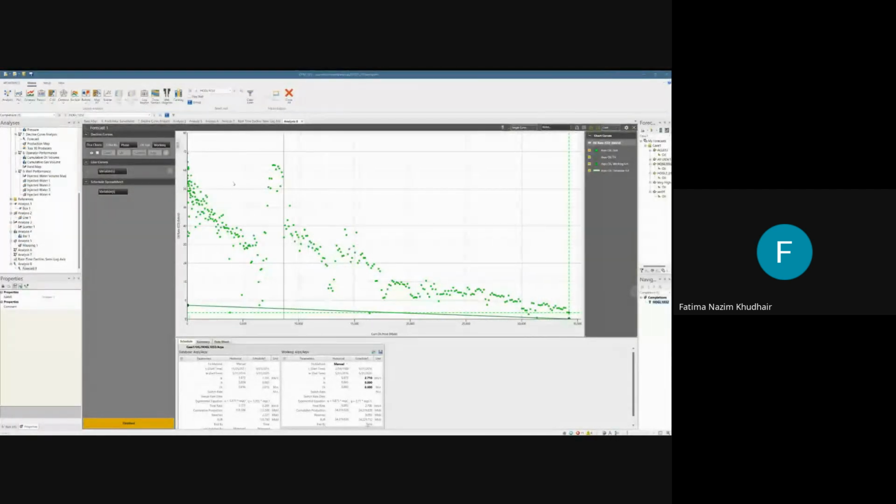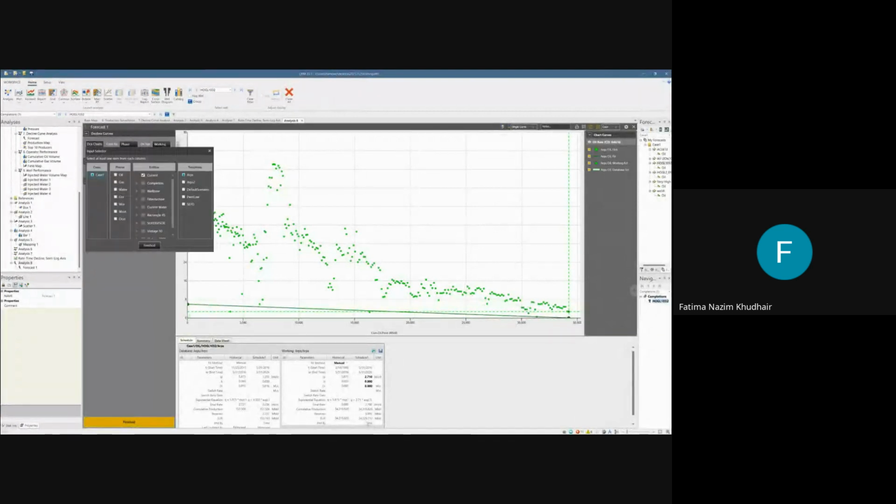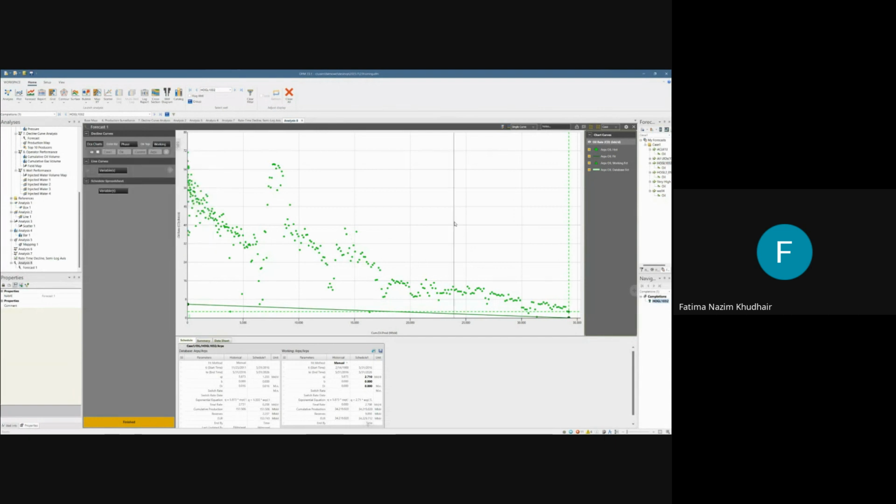Once you open forecasting, the forecast will be automatically generated here because you already set your template. All what is needed here, you come here to pick your case. We have case 1. And then you have to pick your phase, the phase you are making your forecast for. If it was oil, gas, water. For us, in this case, I just specified my variables for oil and gas. And in entities, you can pick your entity. I'm going to leave it on the current. And of course, the template, let's use ARPS. These are the templates that I already have created. And just click finish, and your forecasting will be done. Click finish here.